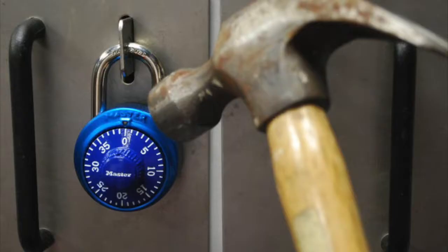High toughness means that a material can absorb a large amount of energy from an impact without fracturing. This is important to consider since some materials can have a high tensile strength and shear modulus, however they can be easily shattered with a sudden force from a hammer. A low toughness would not make an ideal shackle, and thus a high toughness value is required.